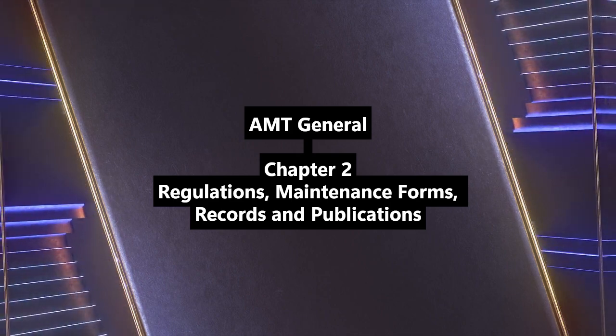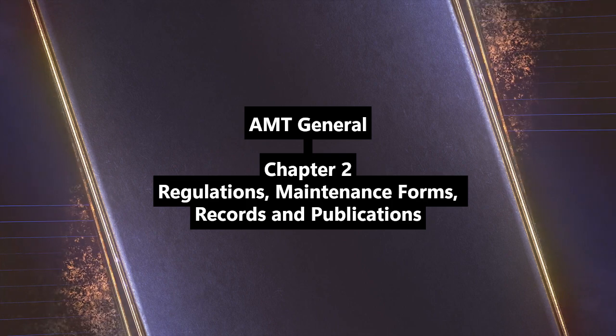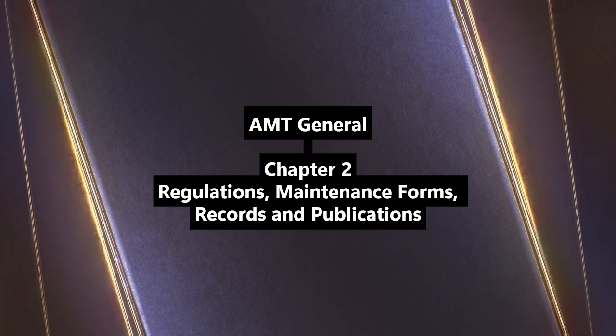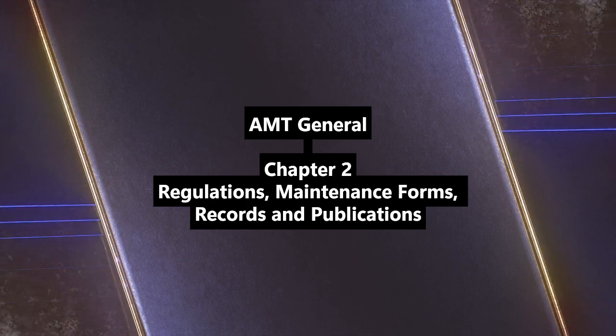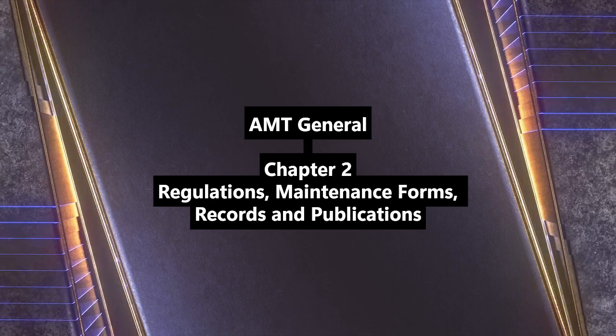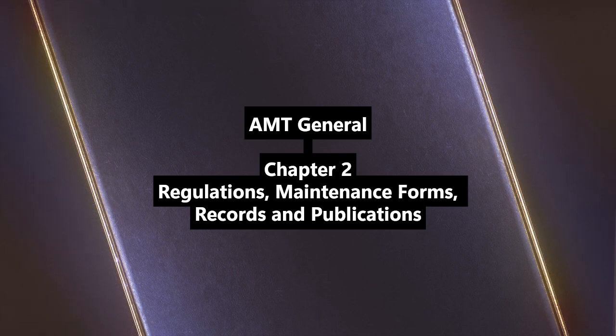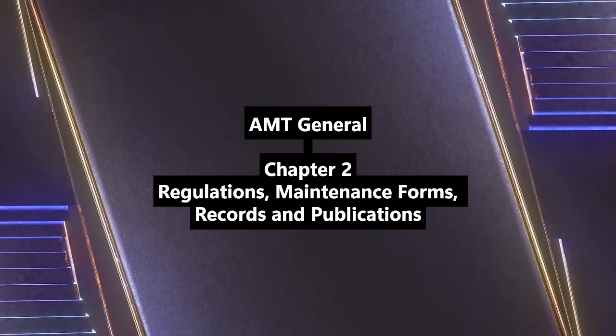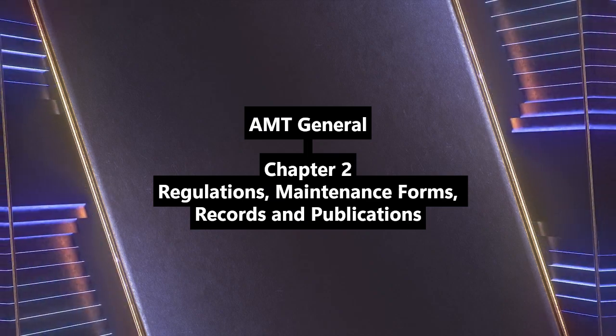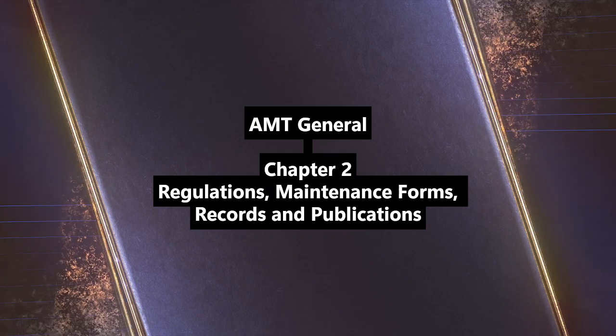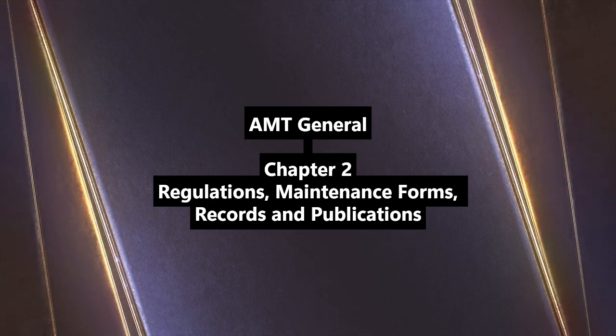And FAA Form 337, Major Repair and Alteration. We discussed this under Part 43, Appendix B. Documents major work, needs approved data reference, IA or repair station signs off, copies to owner and FAA. Repair stations can use work order for major repairs, third copy on board for ferry tanks. Exactly. A crucial form.